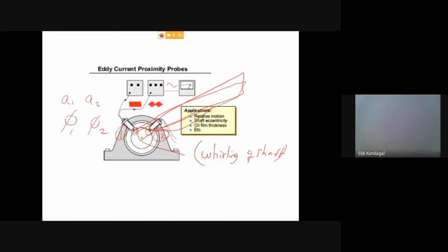The frequency bandwidth you can also see. The larger the accelerometer, the lower the frequency you can easily measure, and the lower the weight, the higher the frequency bandwidth you can measure. For general purpose, medium weight and sensitivity, and for small, light, and high frequency, one can utilize these accelerometers.